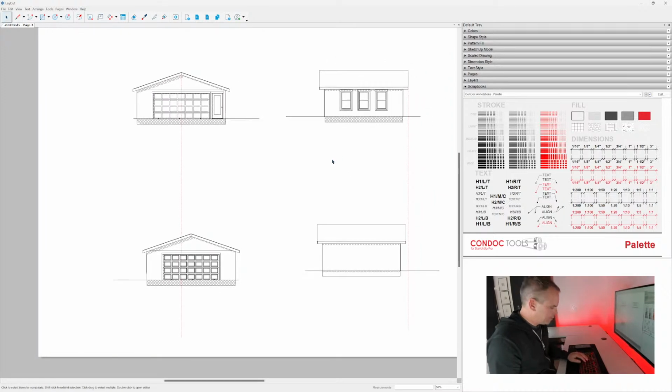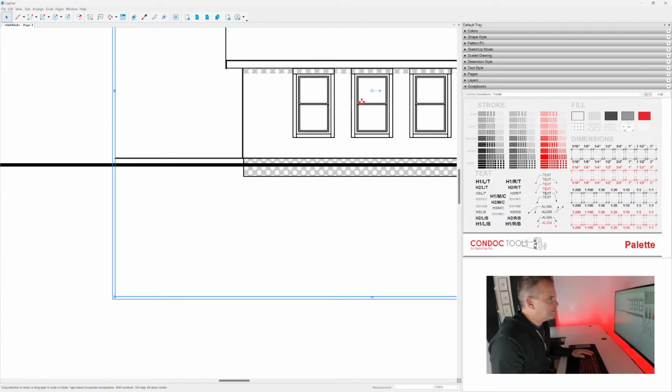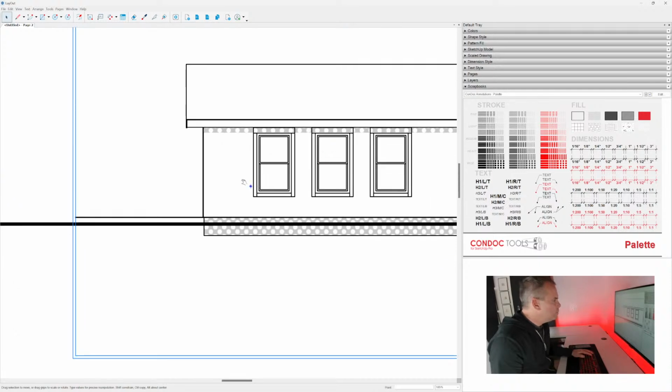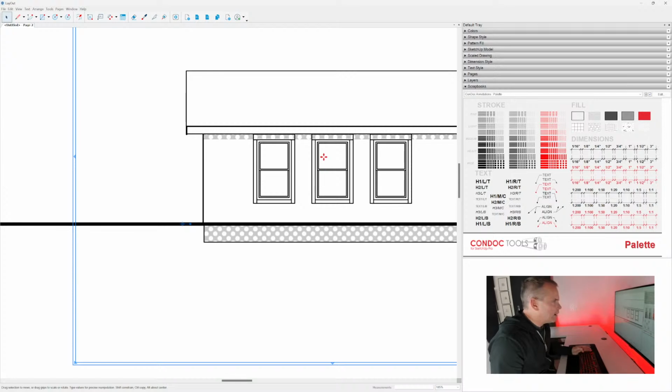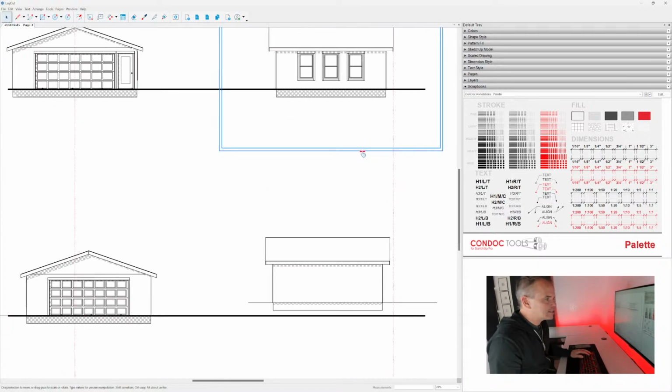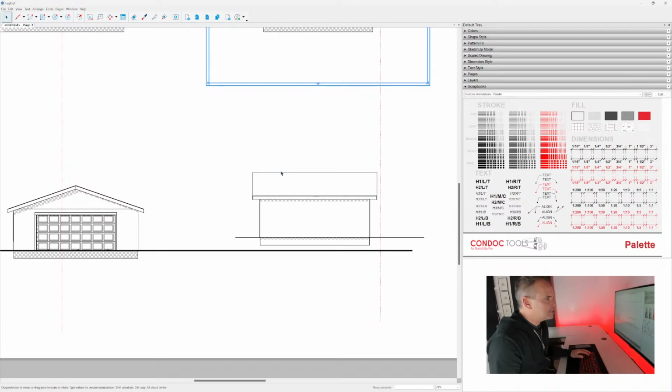And also, I'm going to draw a line, like a nice thick base plane like this. And then perhaps I'll make a copy of it down here. So now what I need to do is get this guy, so take this drawing, move the precise move grip, and also I always right click and turn off grid snap. I hate grid snap. And I'm going to scoot this straight down. To constrain the axis, I can hold shift. So now these guys sit on the same base plane.